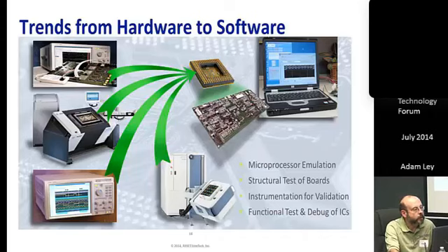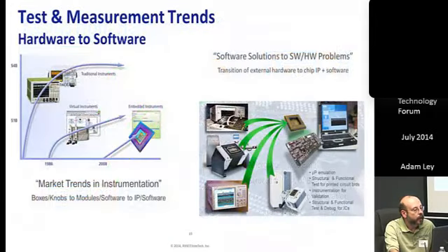That was one of the first areas of instrumentation to give way to the embedded methodology, and you had the implementation of what's called on-chip emulation or in-target probes, where you have access to the debug facilities on chip, also known as on-chip debug or OCD.